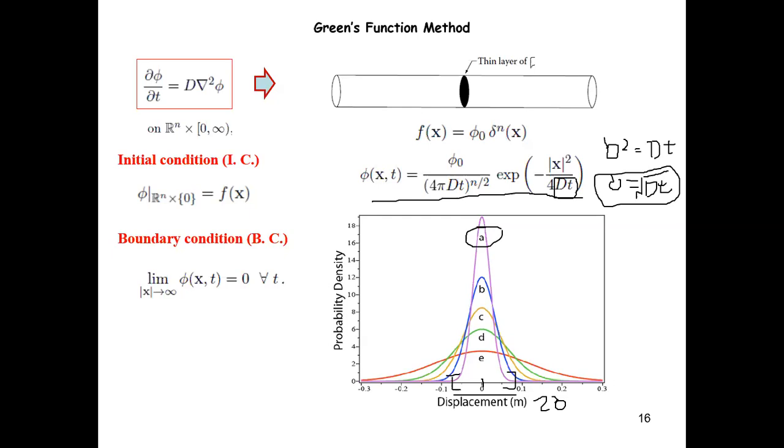So basically this is a solution. We went through all the trouble to get the solution, but you see that it encodes a very useful rule of thumb that we already know, right? In most engineering applications, people do not go back to this full solution. They just work with Dt and square root of Dt, right? If you have a bar of certain length and you know the diffusivity, you use this number to estimate how long you need to keep this bar at this elevated temperature so that, roughly speaking, the carbon can penetrate the whole bar or things like that. This is how they use this.